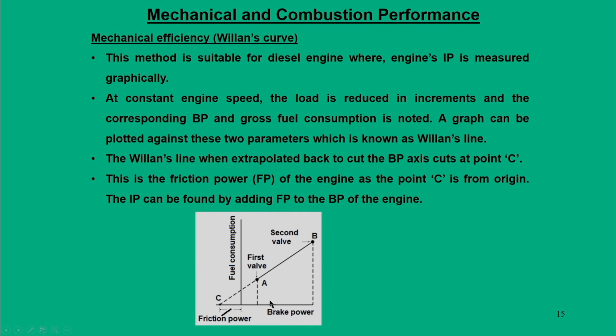Normally, when we want to increase the brake power, we should increase the fuel consumption. So, when the fuel gets injected, for every fuel consumption rate, we can estimate the brake power experimentally. The first point defines the point at which the fuel is injected first, and slowly for different fuel injection values we can get different brake power.